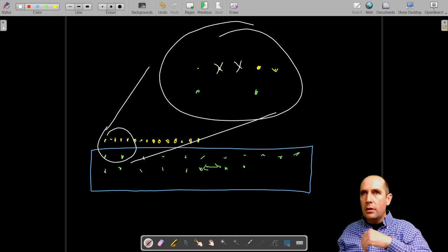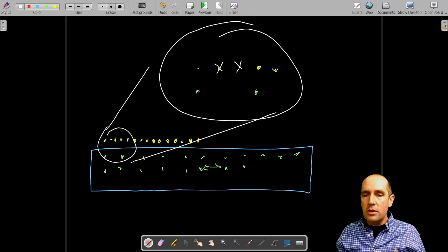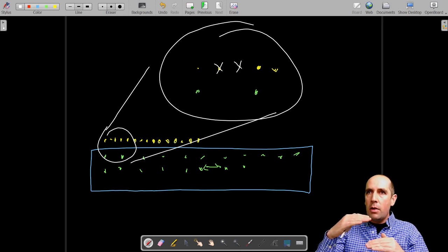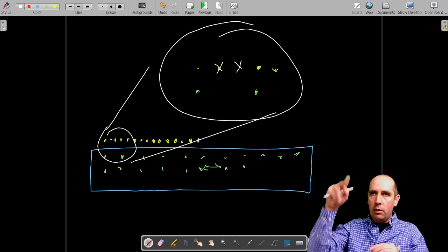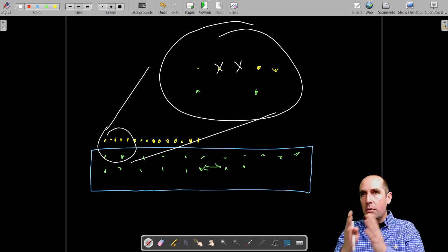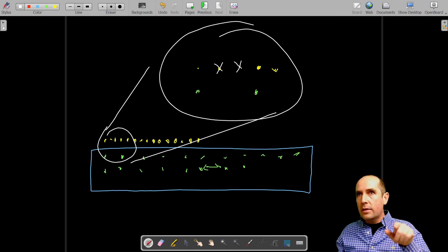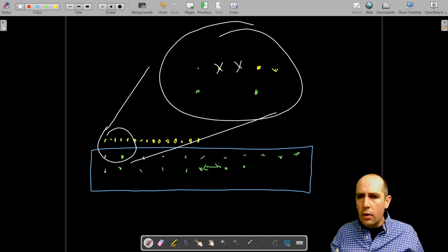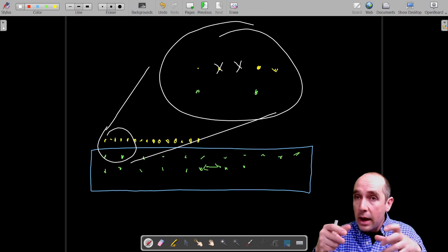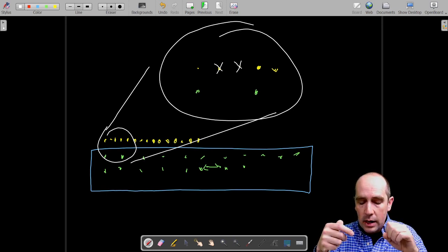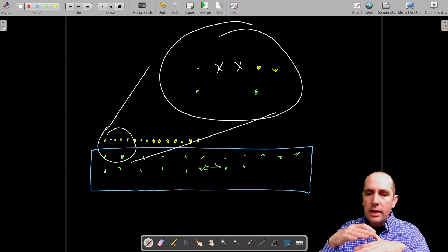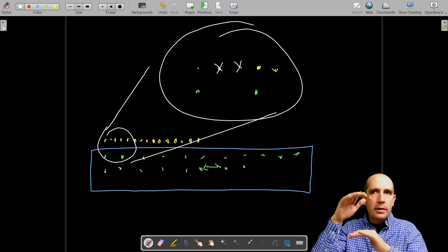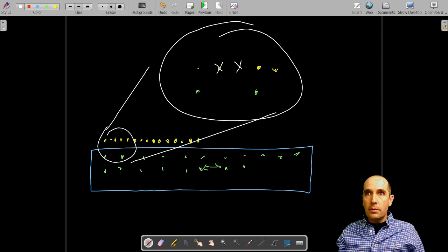And this is the way the quantum cascade laser that I just mentioned was grown, with gallium arsenide layers and aluminum gallium arsenide layers. Basically the barriers are aluminum gallium arsenide, so some alloy fraction, and the wells are gallium arsenide. So with this in mind, one can know that only certain lattices will grow nicely on top of another.